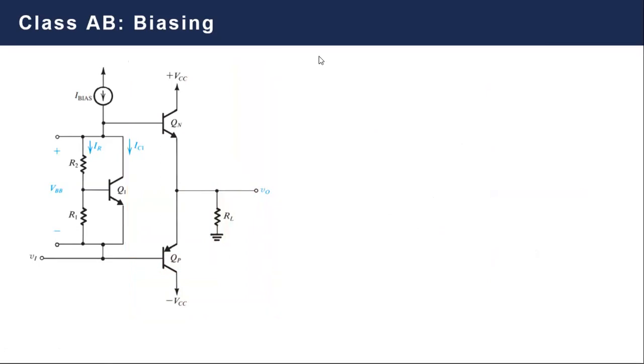Okay, so what will happen? Here we have a current source. Again, assuming a high beta, this current source will go, and then it will be branched. Some current will be flowing into the transistor, and another current will be flowing here. We call this current IR, as you can see. This is the current flowing in the resistor.